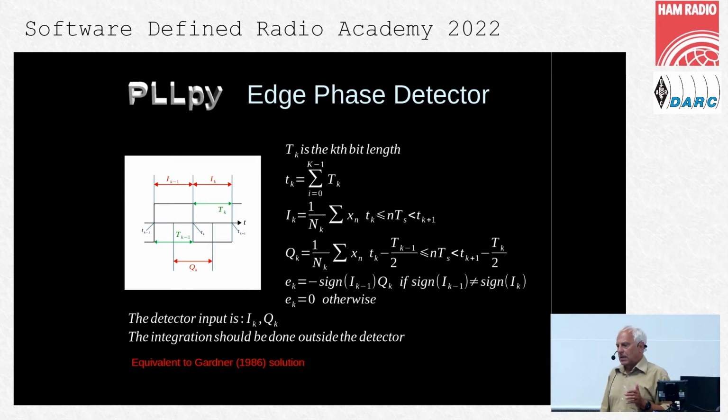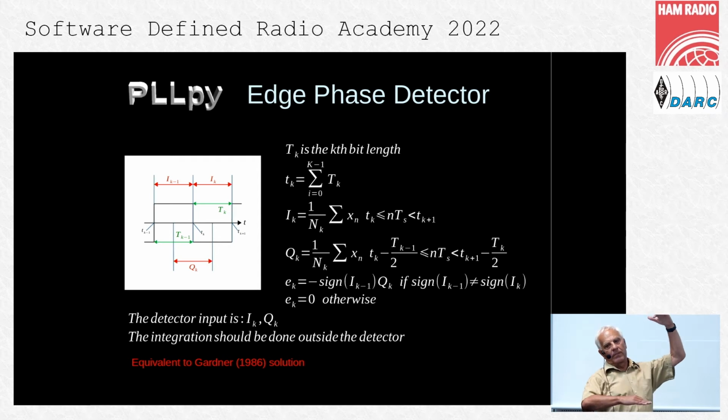That's a very, very, very tricky phase detector. Actually, what it detects, if you have a PAM, the pulse amplitude modulated signal, which has +1 and -1 signal levels, is the level changes. That means the edge of the signal, and compare it to a reference clock and compute the time differences of the edges.